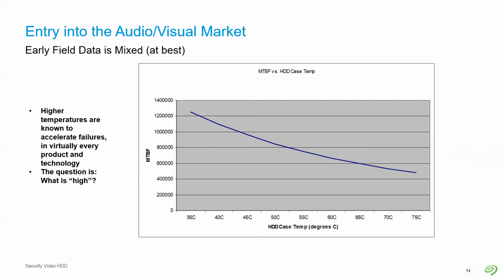So the power density was high. If you have 10.5 or 12 watts that are being consumed by a PC, but the box is 3 feet tall and has 3 fans on it, you can imagine it's an awful lot cooler than something that's been shrunk down to 1/8 of that volume and has only a single 1-inch fan inside there. So power density was a problem.